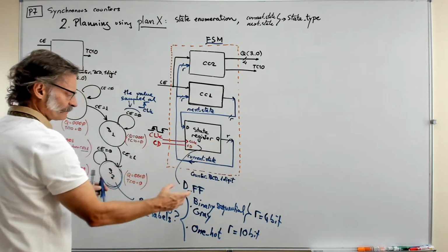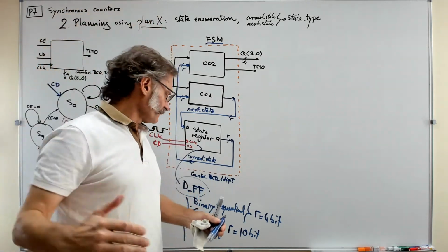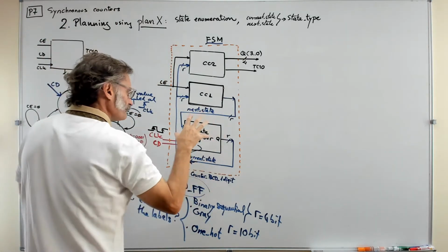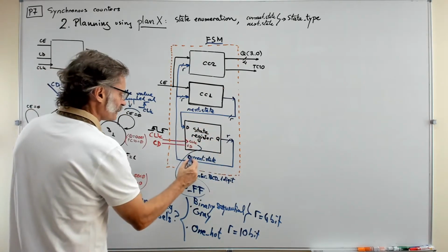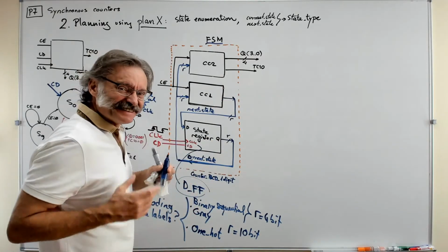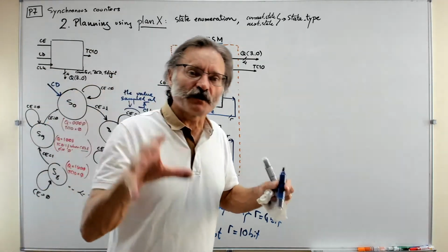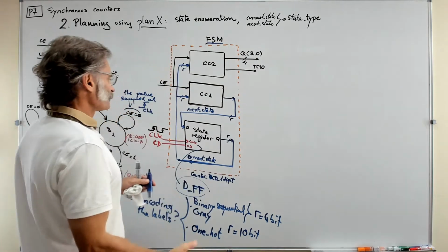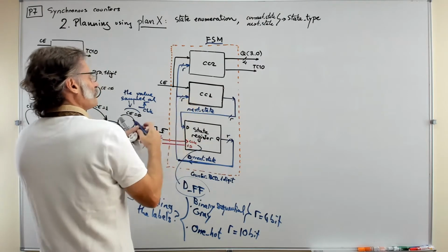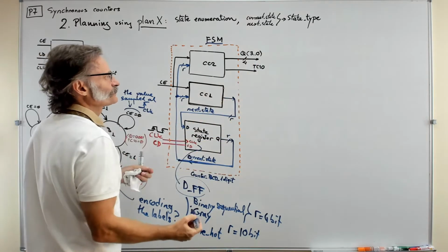The state register implemented using an array of D flip-flops, 1 per bit, and depending on the encoding, you have here the memory of the system. So the current state, in some way or another, is keeping inside the machine this internal state. That means the label. The machine knows in which label you are by means of a binary combination. So depending on the label you are, and some external inputs, you generate the next state to go, you see?